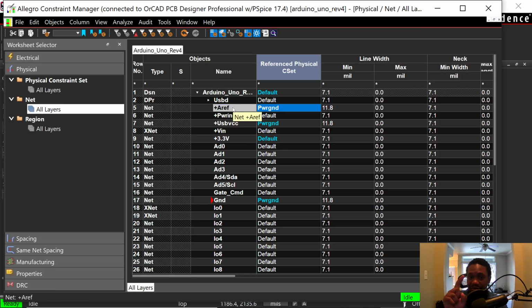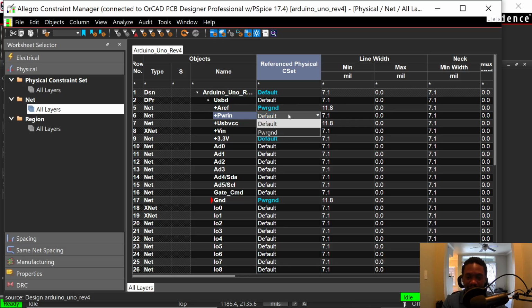When you're looking at a schematic, or when you're designing a schematic, you would put that in your notes so that the PCB layout engineer, whether that's yourself or someone else, knows to apply it to a particular net. Okay? It's very helpful. That's what notes are for in the schematic. And then you have entire regions.